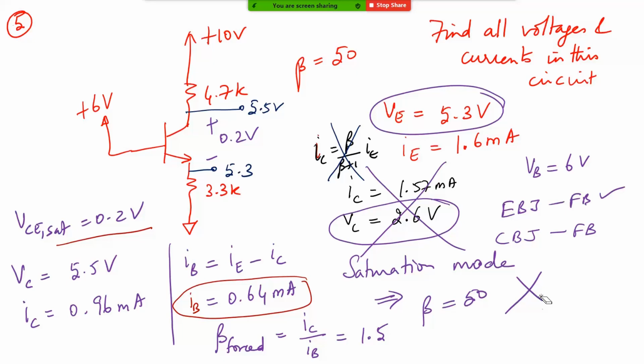In that case, can we supply VB of greater than 1 volt? It depends on the transistor. You have to look at the data sheet of the transistor. What we typically use for normal applications is something like this. This is what you'll be using in your lab, and what you'll typically be using in your projects also. There are some specialized devices for specialized purposes, for which you need to consult the data sheet and then find out what the nominal voltages will be.